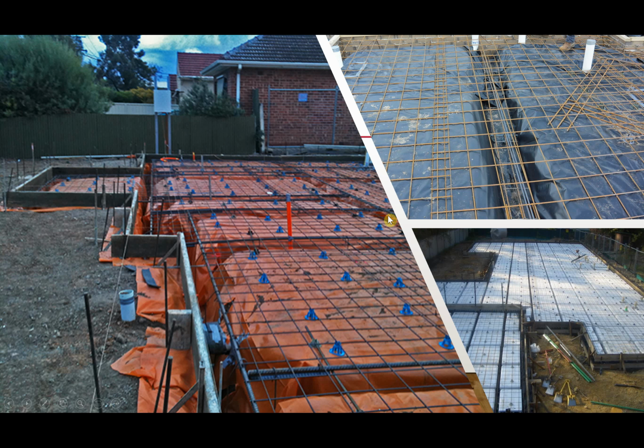After that, they put on this Forticon. So this orange stuff here, which is also this blue stuff here, is called Forticon. That's the brand. It's a damp-proof membrane. So what it does is it stops any moisture from either coming up through the ground or coming down into the ground. Okay, this protects our steel and stops our building moving. So our steel fixers will come in, tie all the steel together, and then we pour our concrete on top of it.